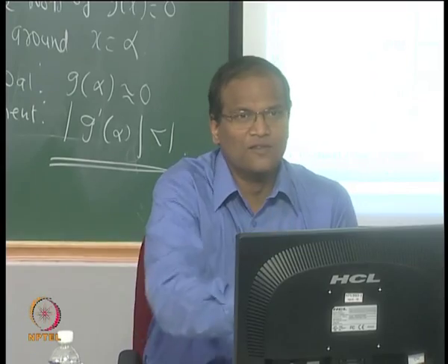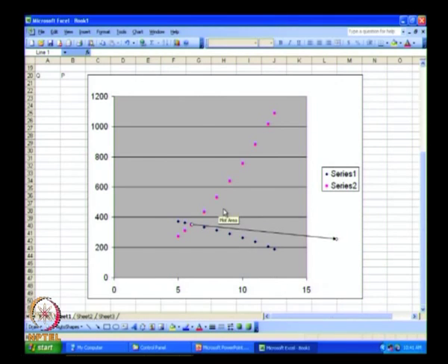Can we draw two more curves on this? Yes, with the same x-axis values. I want to generate two more fan curves for the same duct curve, and they are related to the original fan curve. Are you getting the point? This curve, if it gets shifted here, what happens to the operating point? We know that it goes up. Just graphically seeing that. Can somebody do it, or we'll just give up and go to the next problem? Give up. Okay, that's good. That's the spirit.